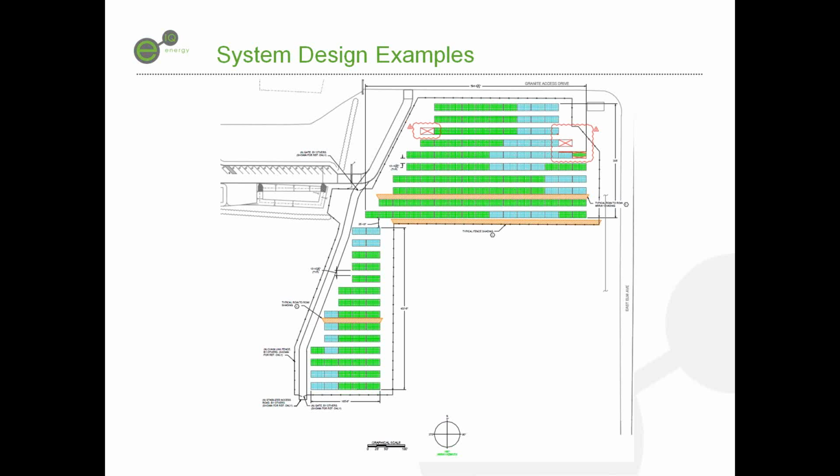But this was relatively easy to design utilizing the vBoost system because, once again, each individual vBoost is always delivering whatever voltage it needs to provide for that inverter to have power flow from that particular vBoost unit. So what that's saying is the vBoost unit all the way up here in the corner, my inverter here is running at 330. This vBoost unit all the way in the far corner might have to run, you know, a few hundred feet, maybe 700 feet to get to that inverter.